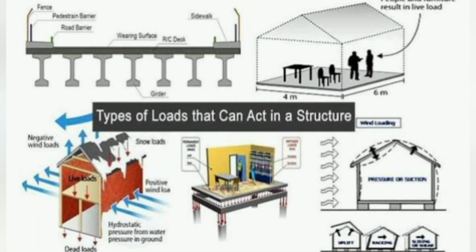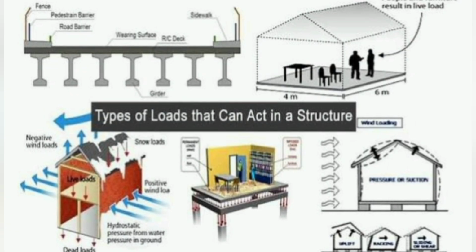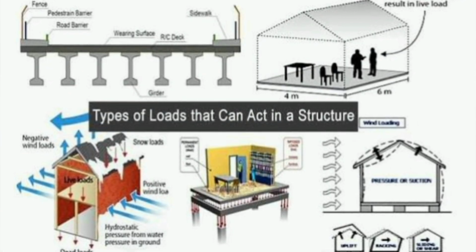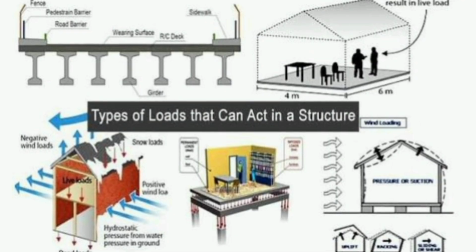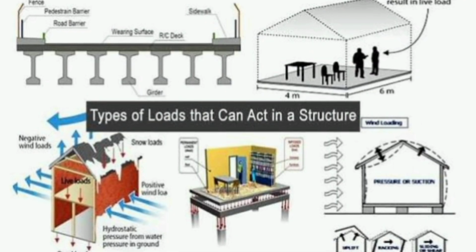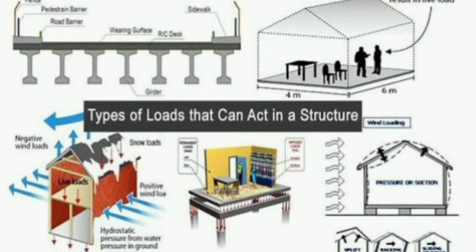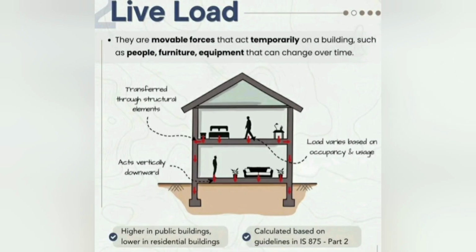The architectural implication here is massive. The required live load directly influences the depth of your floor beams and the size of your columns. If you're designing a flexible space that could one day change from offices to a filing archive, you need to communicate that to the engineer so they can use the appropriate live load from the start, avoiding costly structural reinforcements later.